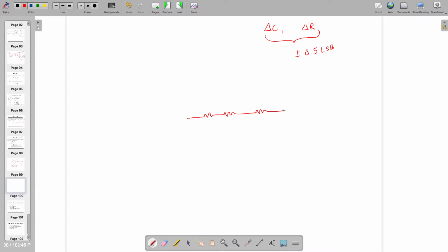So what you can do is keep some extra 2 or 4 or maybe 8 or more resistances, which might be binary weighted, or you can make it thermometric weighted, or many other weightings are available, and you can add some switches.